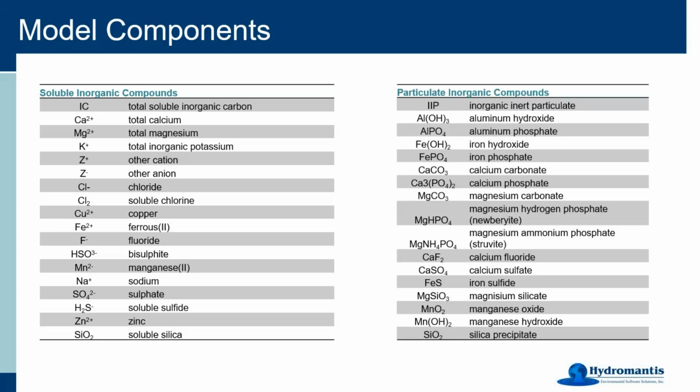The other part of it is that every water treatment plant system relies on quite a lot of precipitation reactions. As you add new chemicals, they react with soluble components and create some precipitates. So we are also monitoring those precipitates as their own components, so that when you look at your composite solids that are being produced from the system, you can identify what type of precipitates are there and what is the makeup of those solids.